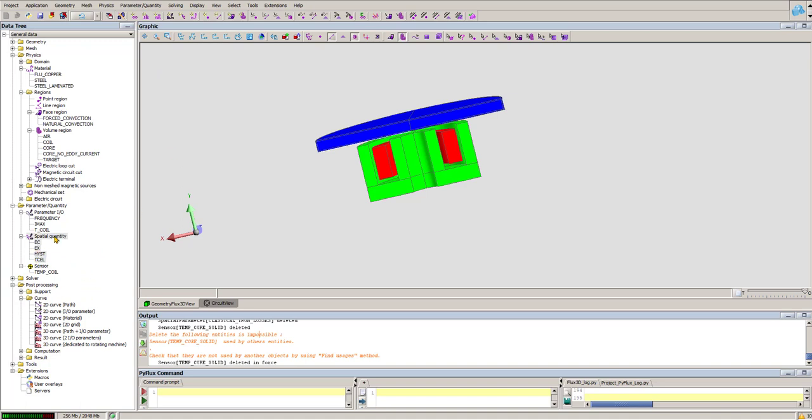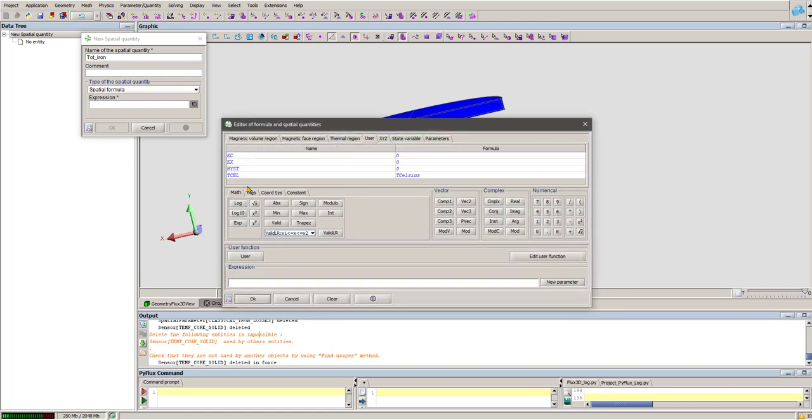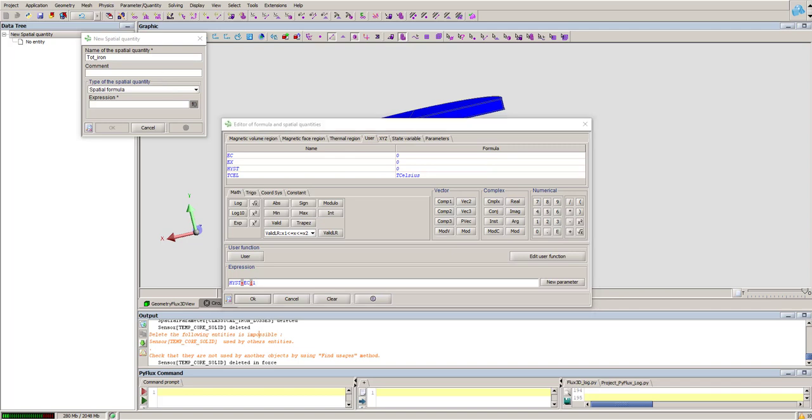What I want to do here is to make the eddy current part of the iron losses depend on the temperature. So I am going to create a total, which I will call total iron, and it will be hysteresis losses plus, here I have to multiply eddy current losses by 1 plus alpha. I don't remember the temperature coefficient of the iron.